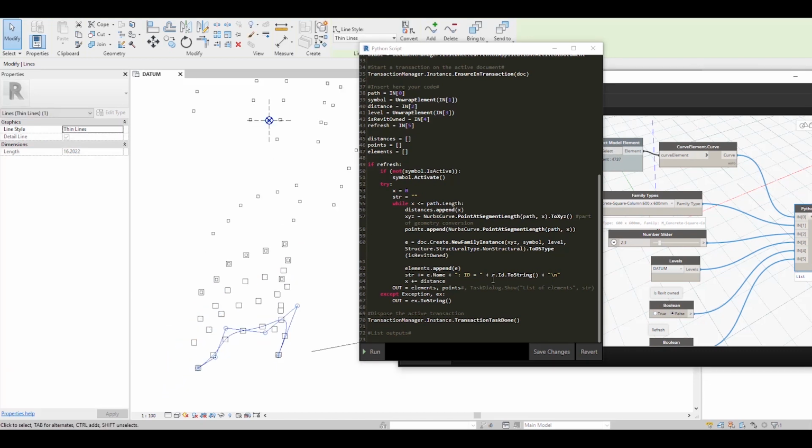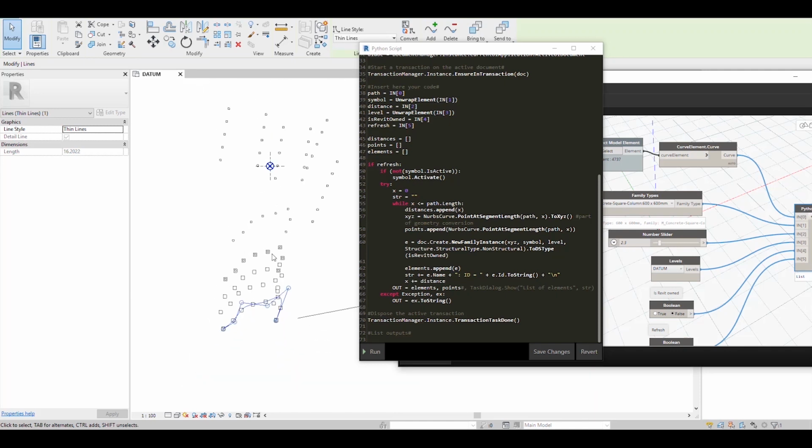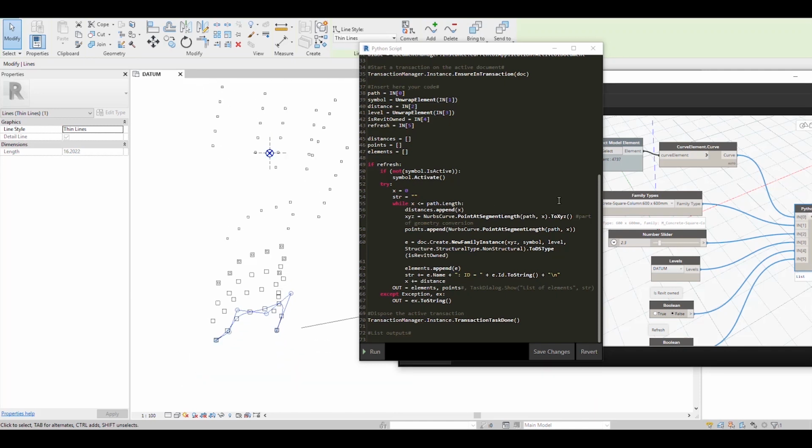So yeah, I can keep going forever, but the main idea is that if you want to bake the objects and store the objects, then you need to make Revit the owner of the object. Otherwise, you can go. It's not reversible. So once it's defined that Revit is the owner, it's just baked and it's done.